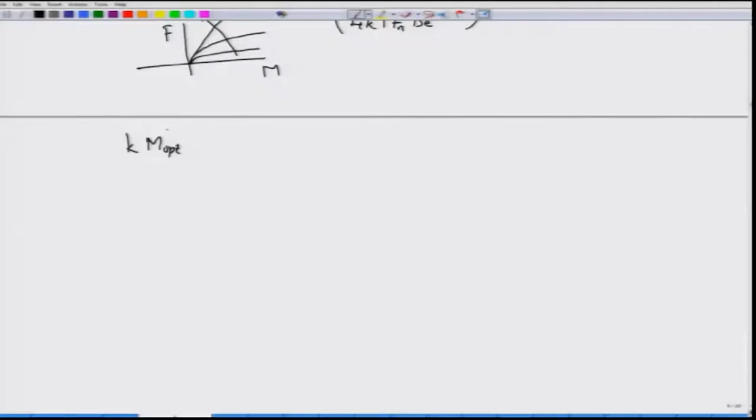You will end up with a cubic polynomial equation, which gives you the optimum value of the multiplicative term m. You get this term by going to the equation for the APD noise variance, differentiating that with respect to m and setting it to 0. I will just leave it as an exercise for you to do that.